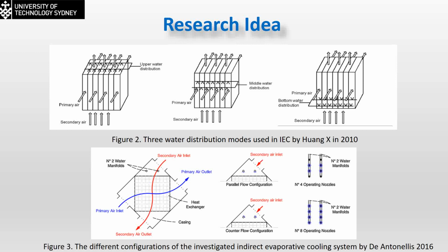The other work is by Antonellis in 2016. He just changed the direction of the nozzles. It's either going to spray the water parallel to the direction of the secondary air at the entrance of the heat exchanger, or he made it counter flow to the air direction. Actually, he got a good result by making the water go cross flow to the air direction, because a pre-cooling process is done before entering the heat exchanger and doing the heat transfer within the channels.